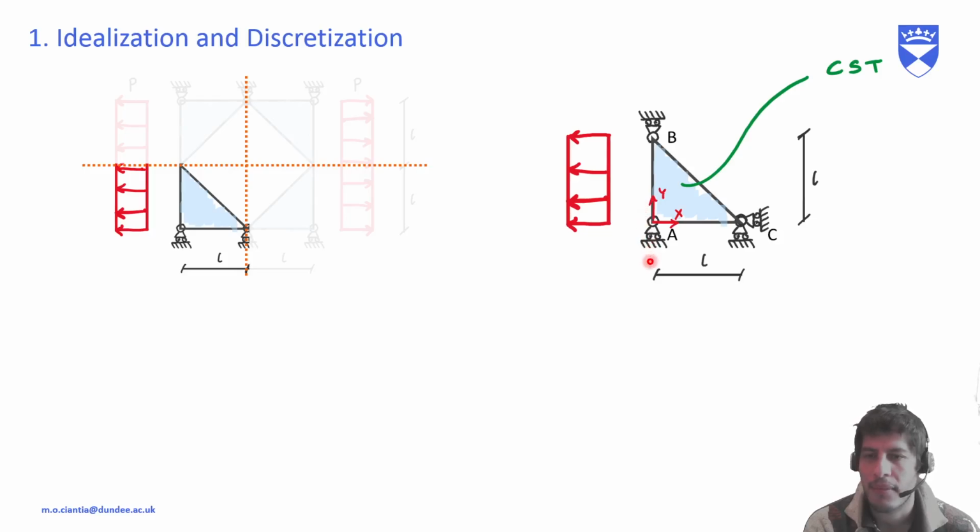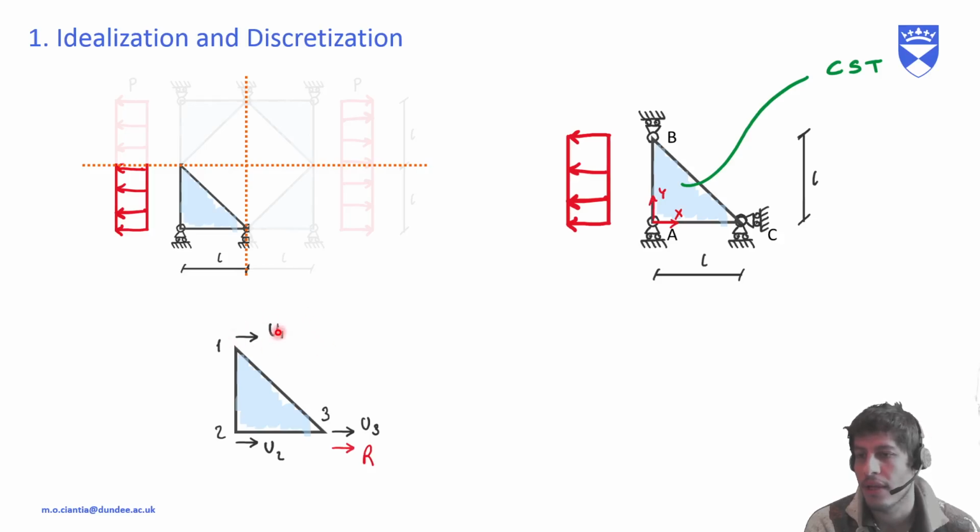And what we then did, as we saw on Friday, was identify the nodal displacements in the global reference system. Here we see that at node C, we actually remove the slider and we highlight the reaction R. We do this because we actually want to determine this value, and this is what we did Monday last week.